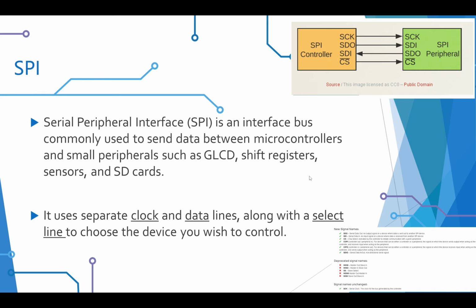So you'll have multiple connections. You'll have a clock line, you'll have a data in and out line potentially, you'll have a chip select line, you might have a reset line, and you might have other lines. And we've got all of those in this because it demonstrates the complexity of what you might have to do. But the majority of those are shared. You'd have a common clock, common data out, common data in, command lines, etc. But the chip select is the only thing that you might actually have different to each particular SPI device, because you can have many of them.